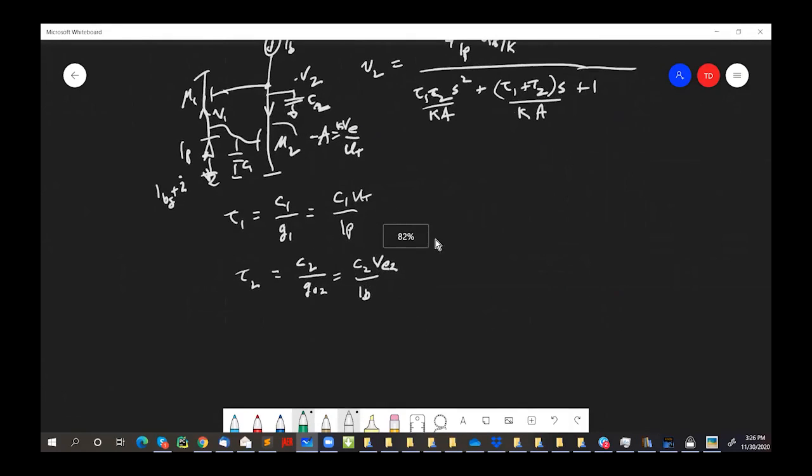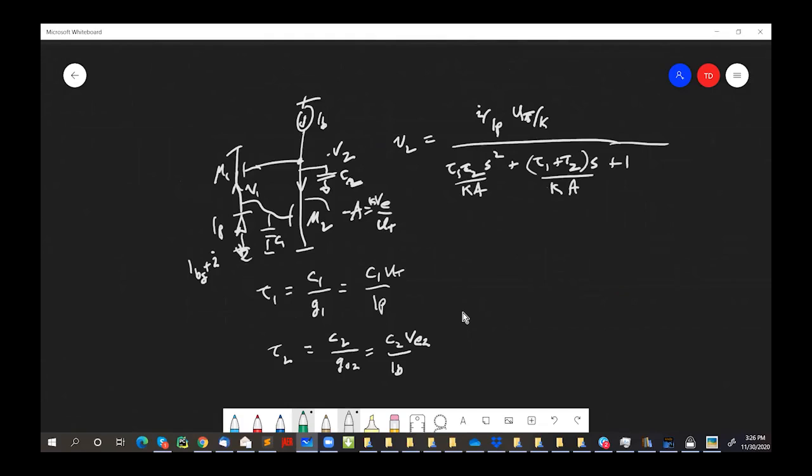Yeah, so it just means that if I were to couple into this circuit at this point with a square wave, and then I look at the output here, does it respond? Does it come back like this, nice and exponential? Or does it come back, in the case of a high Q, instead of coming back like that, go back like this? Right? Be marginally unstable. It kind of represents the unstableness of this second order system.